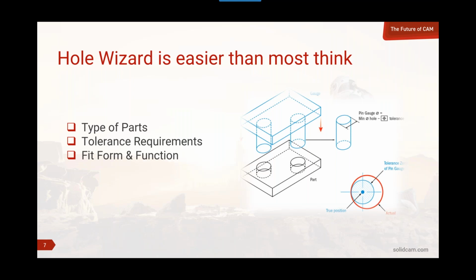Maybe the circle mill is necessary to make sure that it's truly on that position versus allowing a drill type tool to walk a little bit. Okay, so things to think about there.